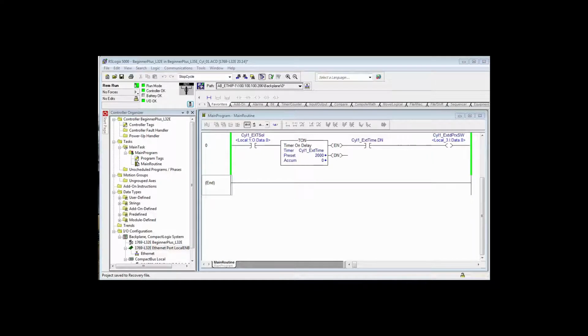This is really simple. If the logic sees that you told the cylinder to extend, now remember, we don't have a cylinder. We don't have a solenoid valve. This is virtual. In your logic, when you turn on output 0, and it'll show up on your LED-backed push buttons on your digital field device simulator, if that's what you're using, when that output comes on, it starts accumulating cylinder 1 extend time.